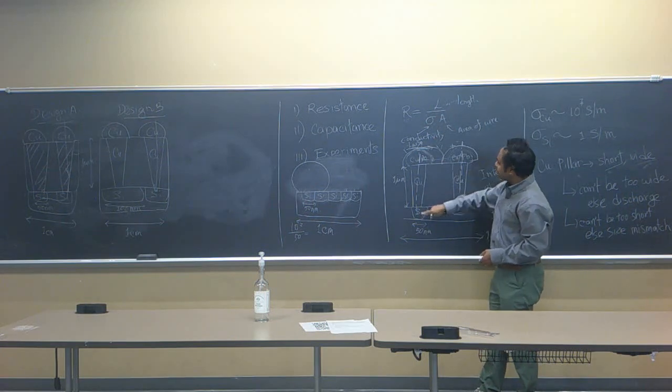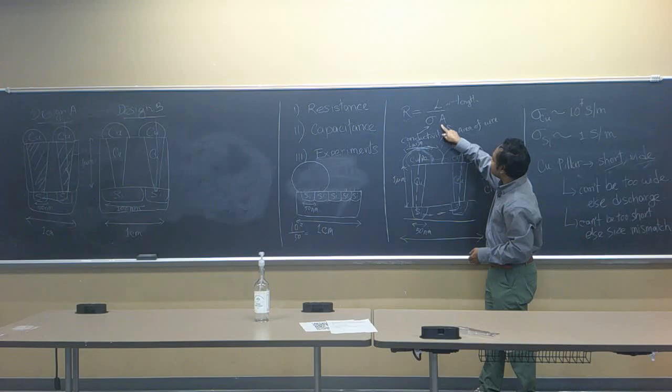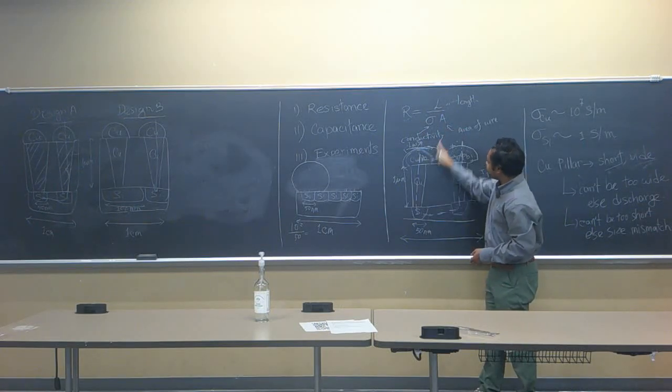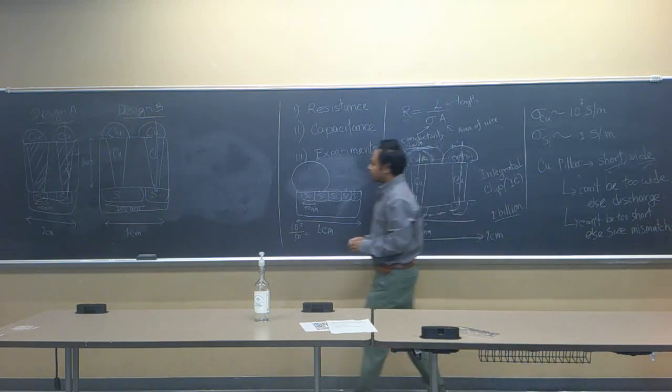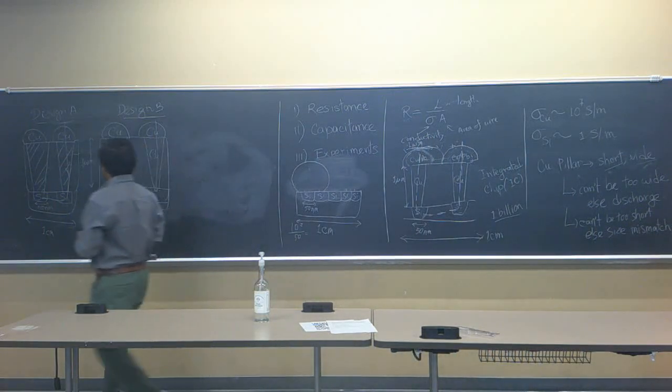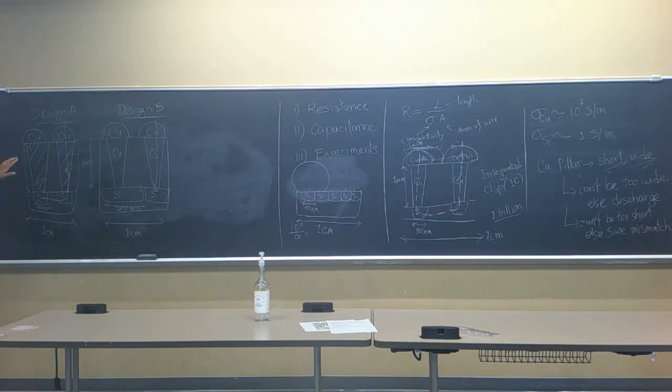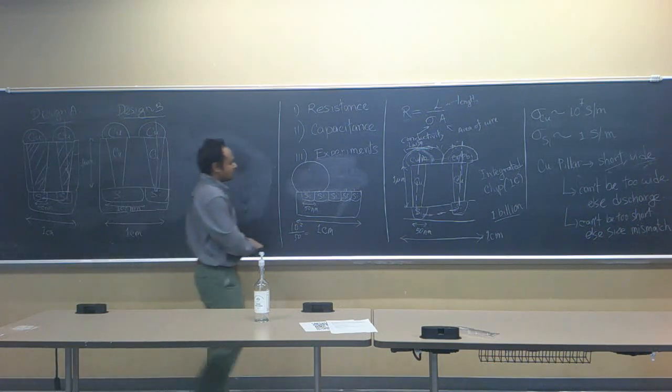At the same time, you can decrease the resistance by increasing the area. So we do not increase the area of the silicon device, but we increase the area of the copper coil. So please keep in mind how the design has to be decided based on resistance. So this is one thing that I wanted to discuss.